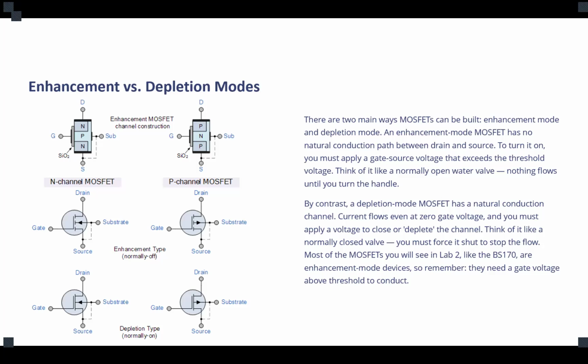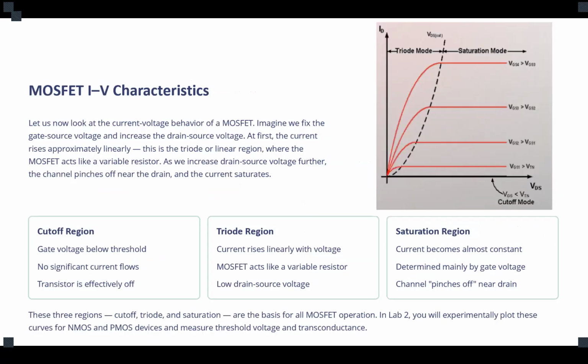Now, in NMOS, as you can see, with the arrow in the middle of the symbol, the current flows from source to drain. And in the PMOS, it goes from drain to source. So this is basically the general understanding of the MOSFET and how we can show it in the schematic of our circuit. Any question from the beginning of the discussion? No?